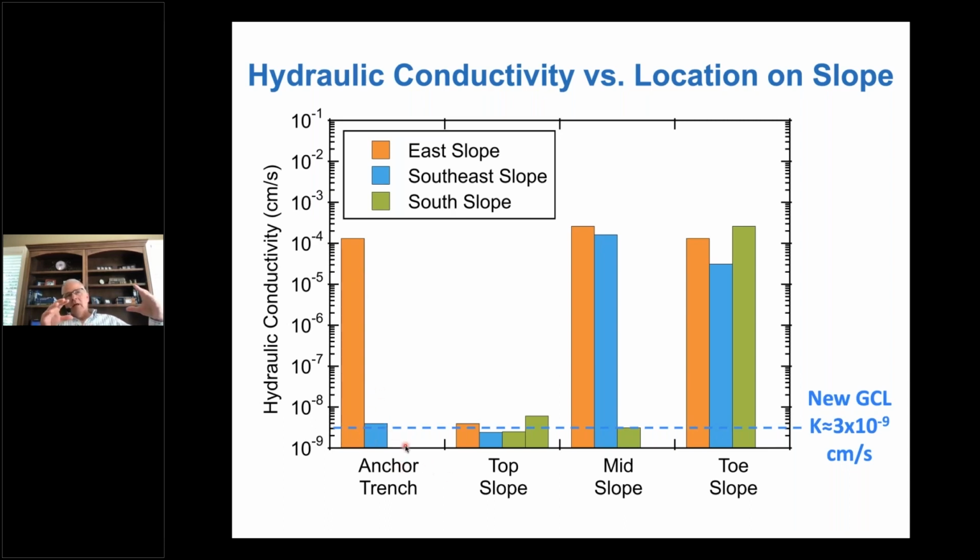If we had it in the anchor trench and that anchor trench accumulated water and then it went through some wetting and drying over time, you can imagine that bentonite, that GCL, is going to become calcic or calcium rich over time. It will shrink and crack, and you saw some of that in the photographs I showed, and become very permeable. On the other hand, it may not dry, depending on where that anchor trench is located, and remain like a new GCL, so highly variable.